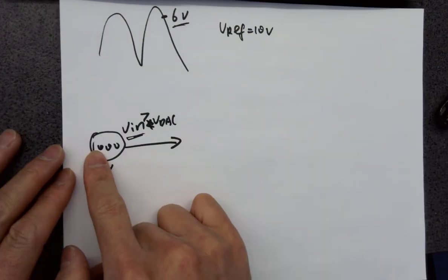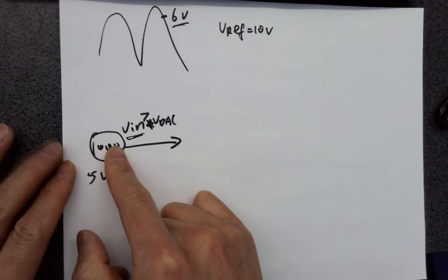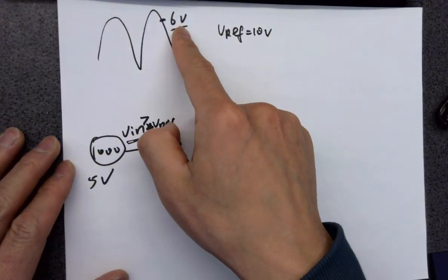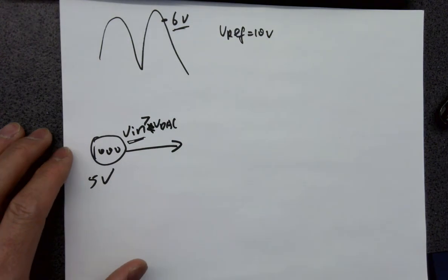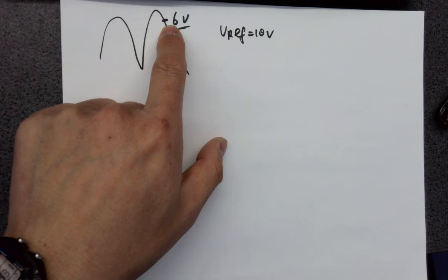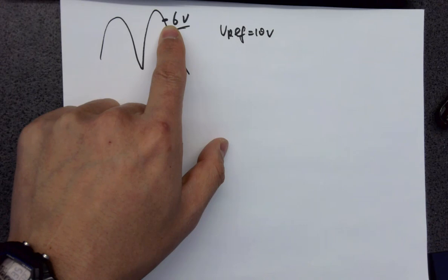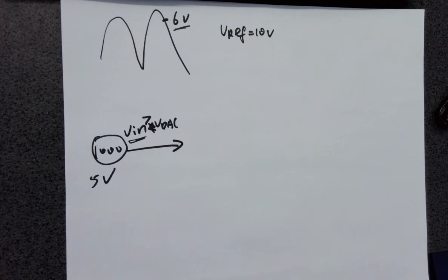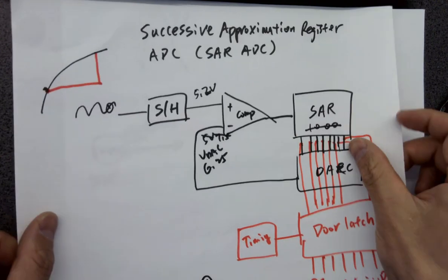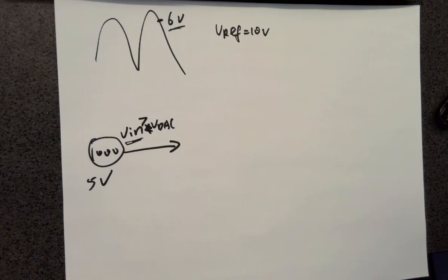Keep in mind, we're shifting the whole thing, the initial number here, to the right by 1 digit. We plug in the comparator's output. 0, 1, 0, 0. The comparator's output, so which is V in? This is V in, right? This is the analog input. So the analog input is being connected to where? Non-inverting or inverting terminal, VP or VM? VP, okay? So VP is larger than VM right now. So the output is what? 1 or 0? 1, right?